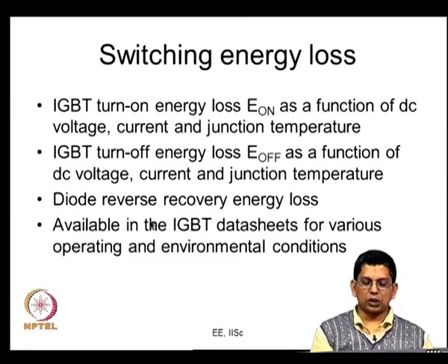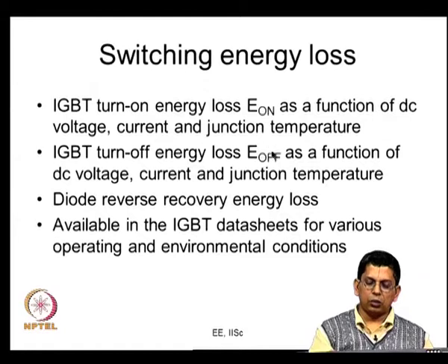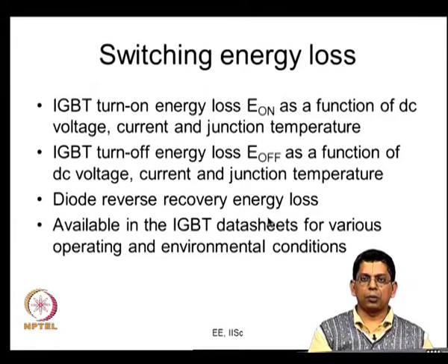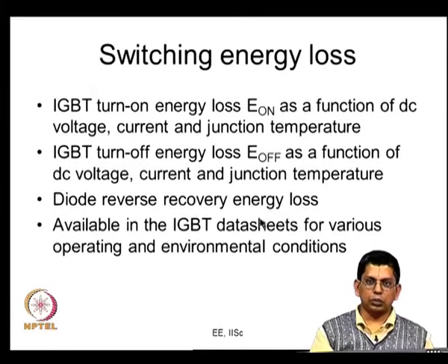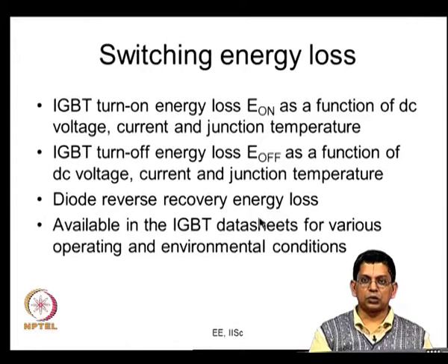Similarly, the diode has what is called the reverse recovery energy loss. There is a reverse recovery process, and there is some energy loss associated with that. So, you can find out how much energy is lost at a particular operating condition, and then look at how many times it is turning on or turning off. So, you will know that the power loss can actually be calculated. This is largely from data sheets.